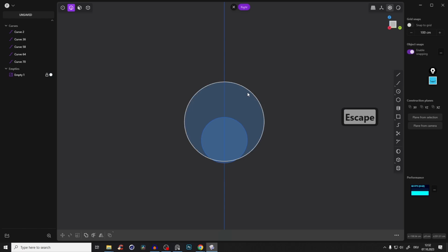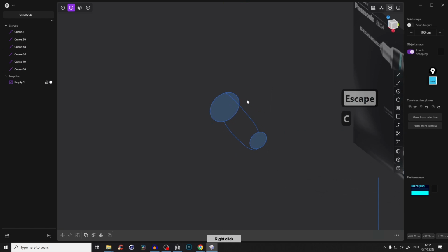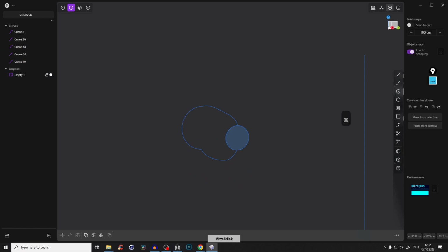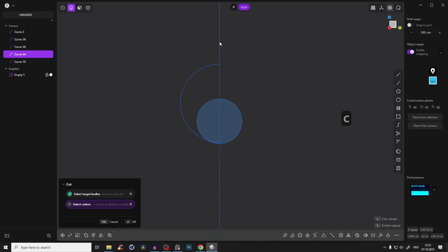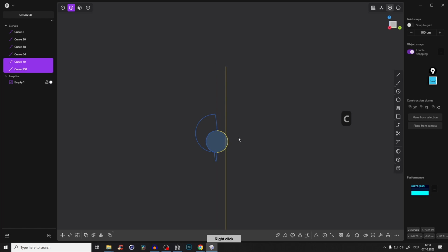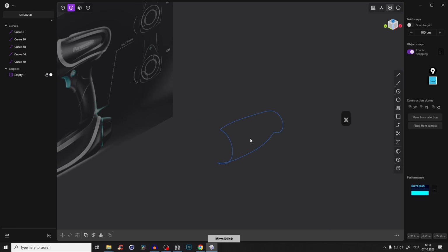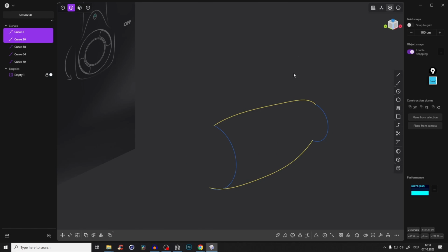Okay, so we select the circle, Shift C, and bam, ready. That's it. And we cut this curve without any searching and all that kind of stuff. So yeah, really amazing. And the same here, select circle, bam, Shift C, cut curve. Okay, you can delete that and we are ready to go. Otherwise, we would search for the commands till Christmas or something.